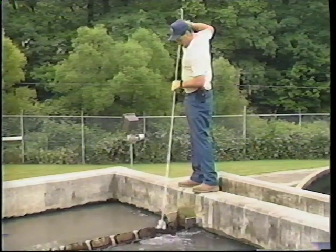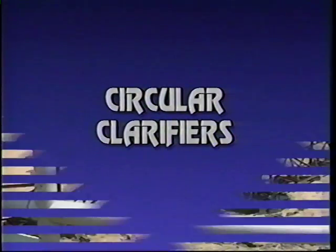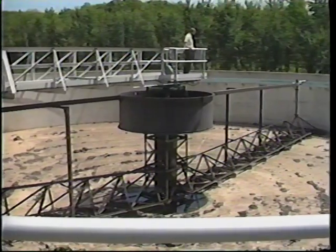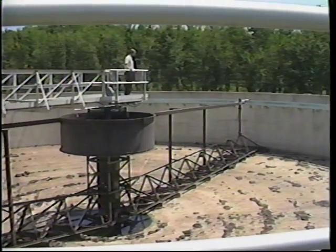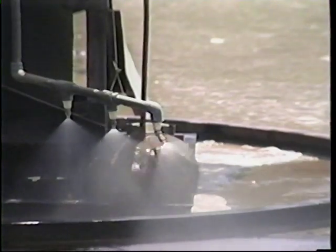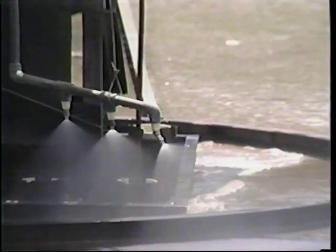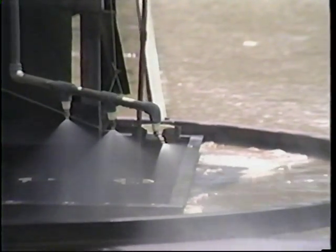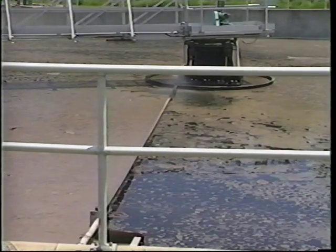Now let's take a closer look at circular clarifier mechanisms. In these units, the wastewater enters through the center column and into the influent well. The influent well is a baffle that slows the velocity of the wastewater and distributes the wastewater evenly throughout the clarifier. As with rectangular clarifiers, the operation of the sludge and scum mechanisms should be observed closely.